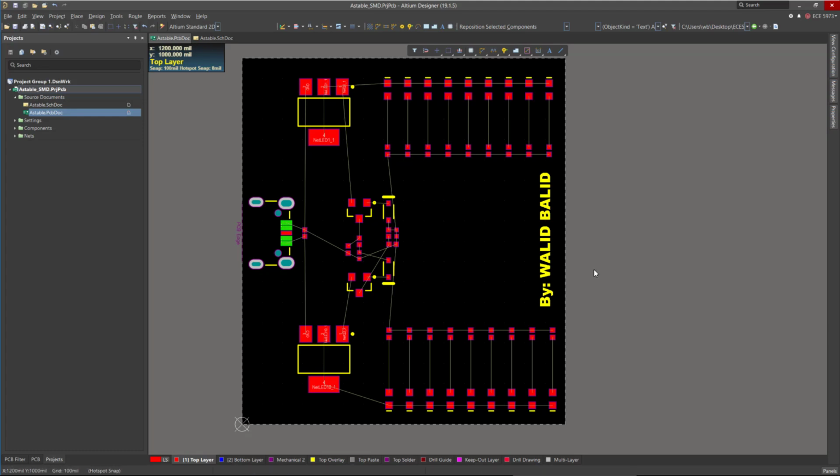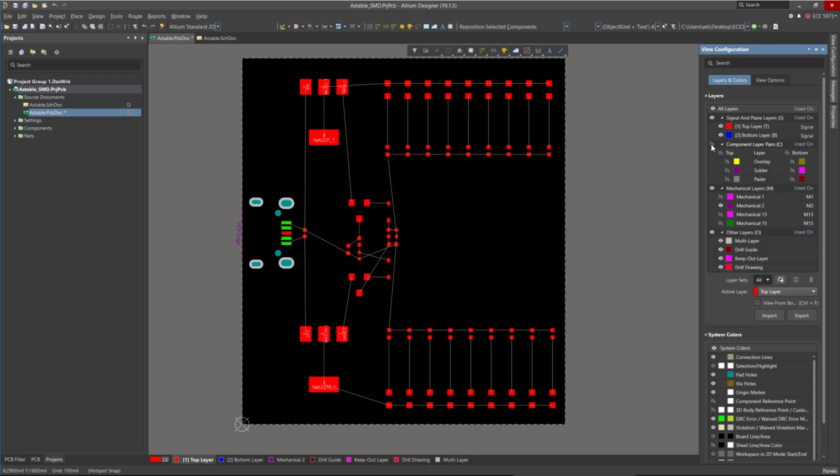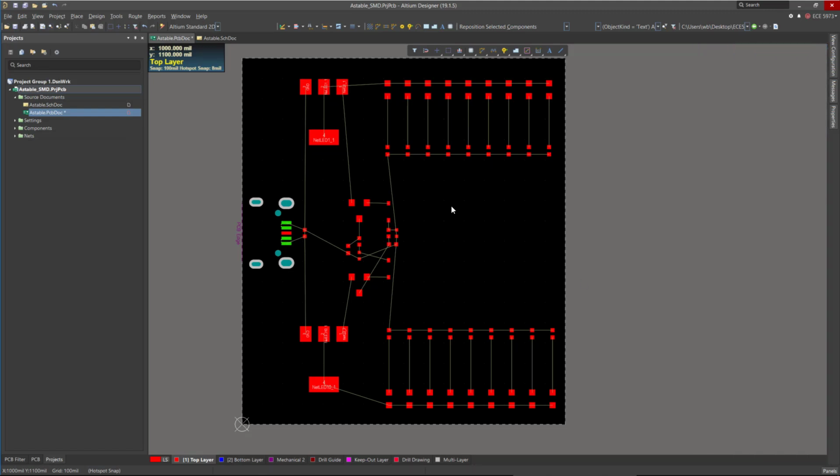To start routing, I always prefer to hide the component overlay layer, so you only see the pads. Basically, these are the pads for the components, the surface mount pads, as you can see here. And the only holes you have here are the mechanical holes for fixing this surface mount connector, a micro USB connector. So let's hide this. Again, the shortcut for routing is Control W, and you will select that. But before we do that, let's go back to the grid, our grid 5mm.